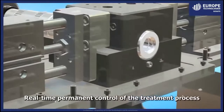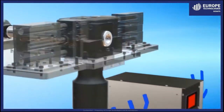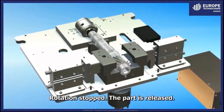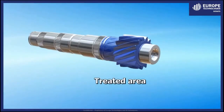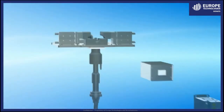Since this takes place in a controlled and sealed chamber that envelops the local area to be treated, there is no escape of media. So at the end, we remove the output shaft from the enclosure and we observe the treated area. This allows the process to use a few grams of high quality media for repeatable peening results. For example, 14 grams of bearing balls can peen 200 parts.